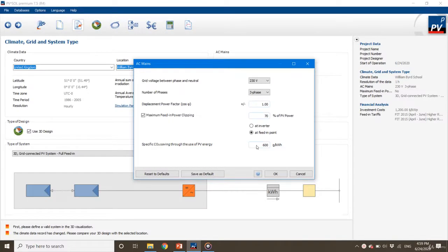Assuming the solar electricity or electricity from PV systems contains nearly no emissions, you can calculate the emissions that you will get rid of through a simple calculation made by PVSol. For example, the CO2 emissions from a coal power plant that supplies electricity is 950 grams per kilowatt hour, and you will get rid of 950 grams per each kilowatt hour if you install the PV system.